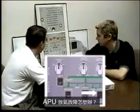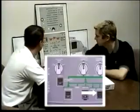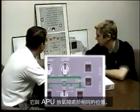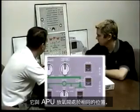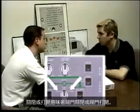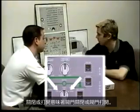What about fault on APU bleed? APU bleed leak only. The cross bleed selector, you told me with the selector in auto, it takes the same position of the APU bleed valve. However, what if I command shut or open? Shut or open is going to give you a shut valve or an open valve.